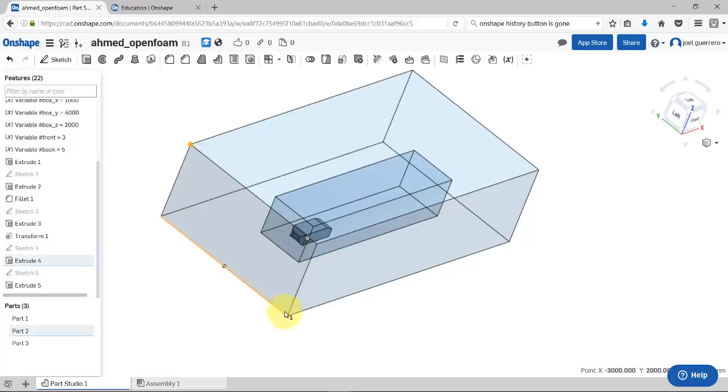Something really helpful is that you can measure distance. So select this one here, and then you have the minimum distance, but you can also select how it changes in delta x, delta y, and delta z. It's really, really helpful, so always look to this right corner, see your minimum distance. You get a lot of information.